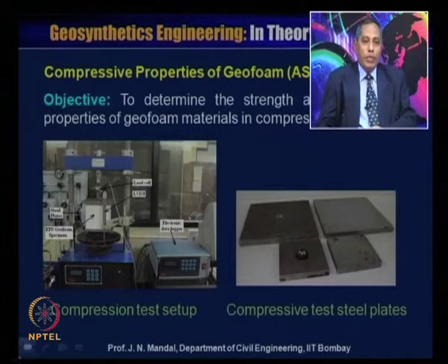So, you should know this when you design any structure using the expanded polystyrene geofoam material. This is the experimental setup in our institute, the compression test setup. This is the load cell, this is the LVDT, and this is the steel plate, and this white color is the EPS geofoam specimen, and this is the electronic data logger.